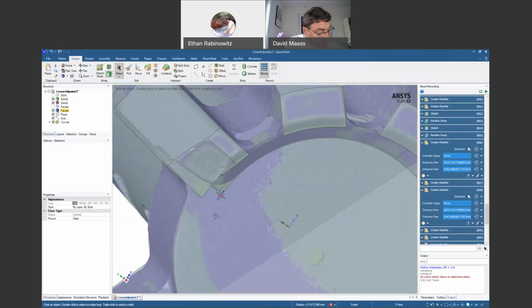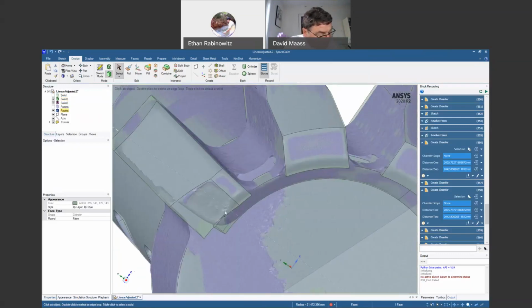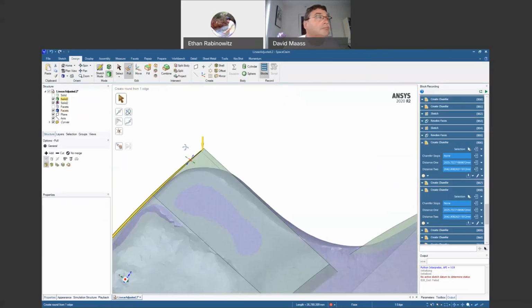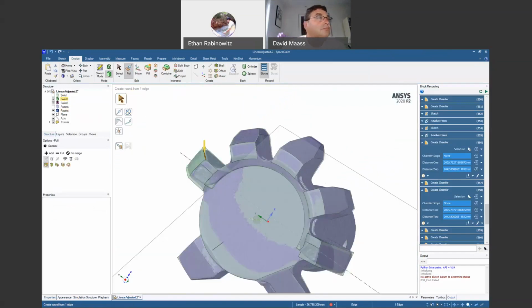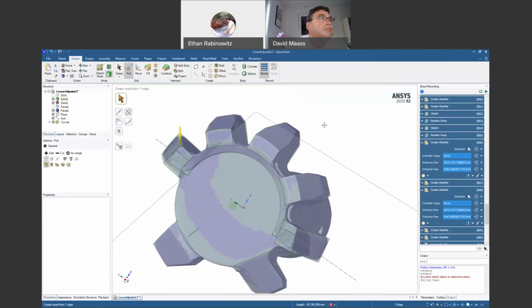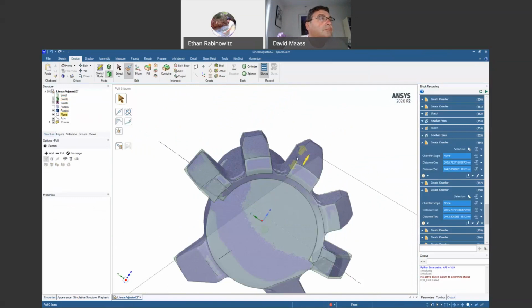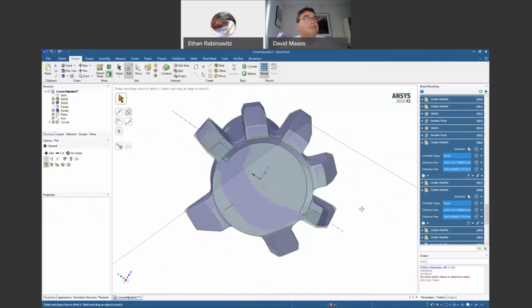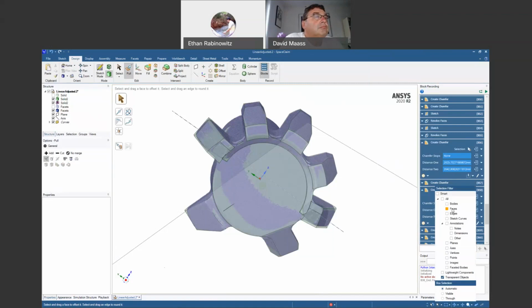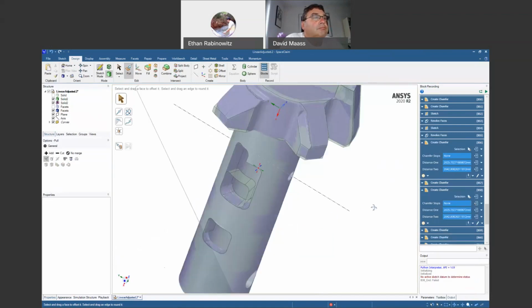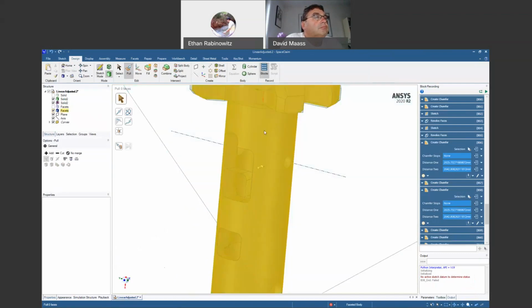And then, once all of the main faces are there, it's a matter of if we want to break all of these edges into small rounds, there's ways to mass select edges. Double clicking will grab chains of edges. If we get to a point where all of the edges in the model need to be rounded, or all the edges in a certain area, you can actually set your selection filter to edges. So let me just hide the facets for a second.